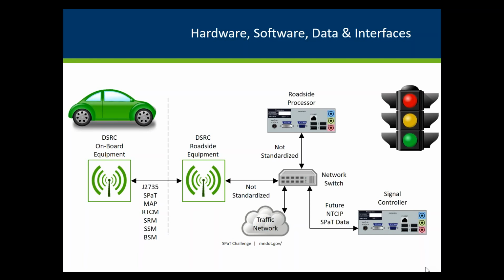We're hoping at MnDOT to make that run in an ATC controller, where there's a standardized software interface, so that hopefully it would run on multiple brands of equipment. And eventually we could actually run it on the signal controller, the same machine, if you're using ATC standard racks.